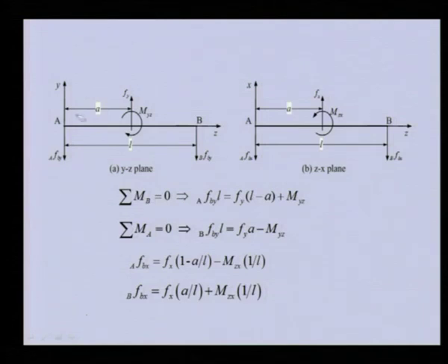You can see this is the free body diagram of the shaft. We have removed the disc from the shaft. The reaction force My and moment Myz from the disc onto the shaft act in the positive directions, because these are reactions.